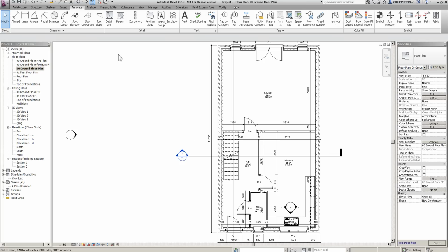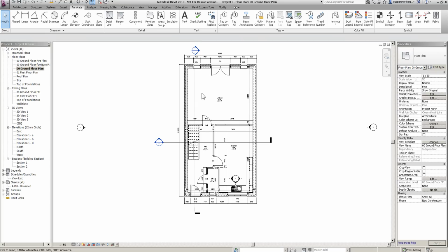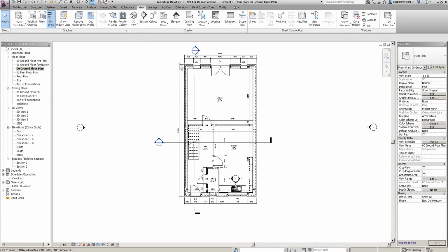Okay, let's just have a little look at my schedules. Okay, we're nearly there now. We're nearly on an hour. I just want to show you some schedules. We're going to get some stuff onto some drawing sheets. Okay, and we're good to go from there. So a schedule, a very, very quick door schedule. Okay, I just go to my view tab over here, schedules and quantities.